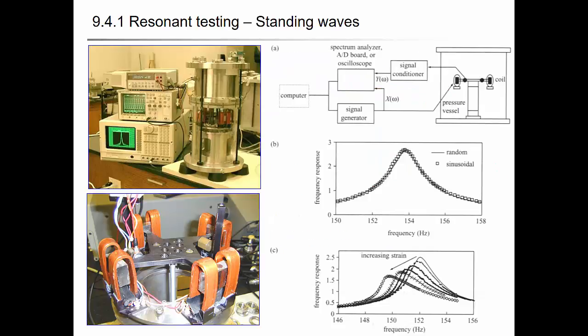Here you have a schematic drawing of the resonant column test. You have a magnet and coil, and at the coil you apply the AC signal, the current or the AC voltage. Then it applies force to the magnet, so you can vibrate the magnet using this coil system.